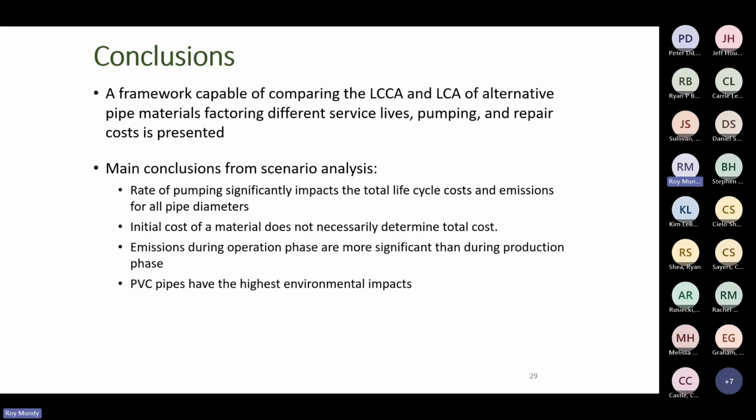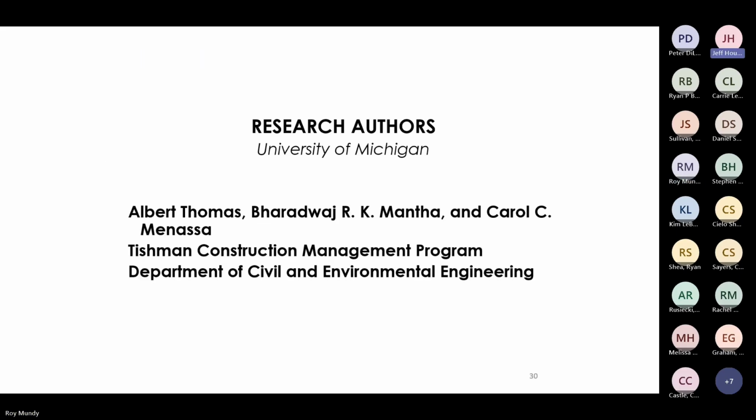And in the main conclusions, rate of pumping significantly impacts total life cycle costs and emissions. Initial cost of the material does not necessarily determine the total cost and value to the customer. And emissions during the operational phase are more significant than the embodied production issue, and PVC pipes do have the highest environmental impact.